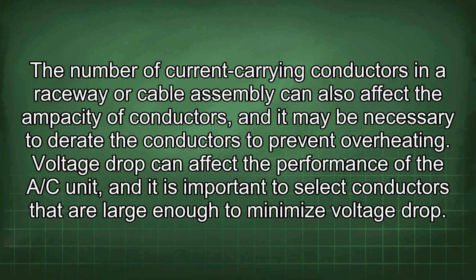The number of current-carrying conductors in a raceway or cable assembly can also affect the ampacity of conductors, and it may be necessary to derate the conductors to prevent overheating.